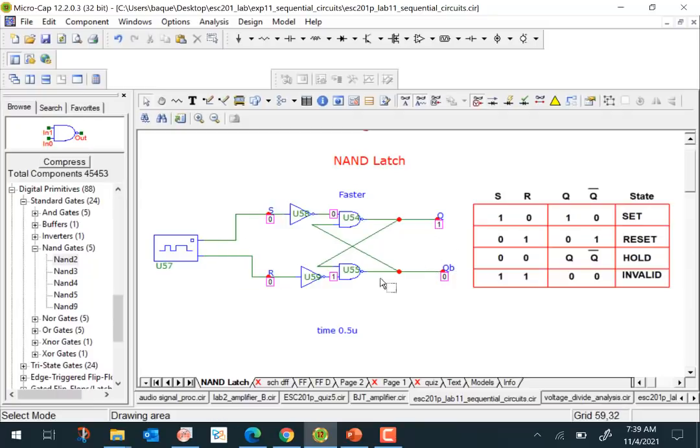And this is what makes the behavior of this circuit unpredictable, because in general we cannot control which gate will have a delay a little bit more as compared to the other. Similarly, these inputs are coming from some previous gate, so we cannot control precisely that both inputs should arrive at the same time, or that one should be faster than the other.